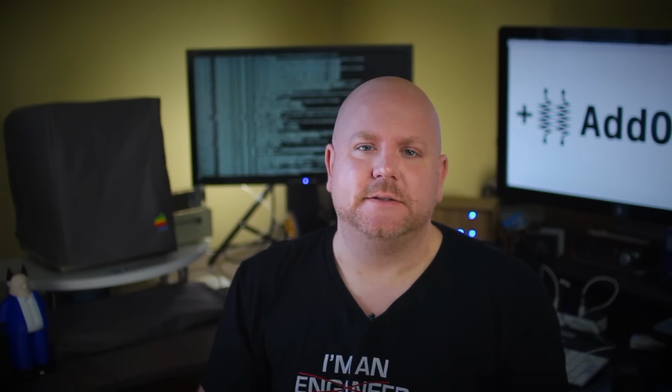Now, in terms of when to select a pull down, about the only time I really use pull downs is in the case of a MOSFET where I want to keep the gate at a low when a system is first being powered on. Or if I have an IC that I need to pull a signal down to 0. It's not something I typically use with buttons.